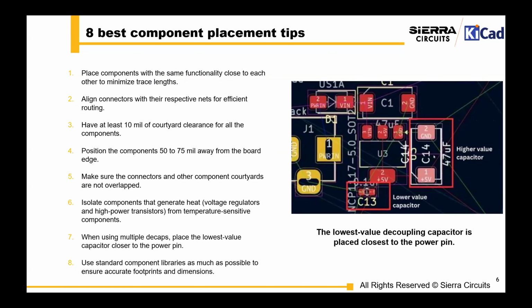Seth, do you have any comments on courtyard clearances or how to design them? Absolutely. When you are designing your footprints, KiCad really likes you to put down a courtyard on the footprint. Your front courtyard can be different from your back courtyard in the case of through-hole components or components that require, for example, thermal standoff to other elements.